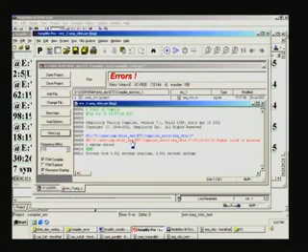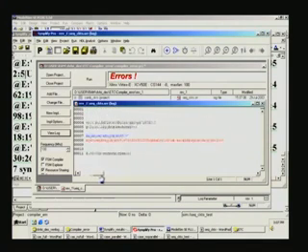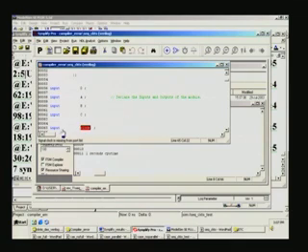It is once again the same, except that this time it is reporting differently. Signal clock is missing from port list, that is what it says here. If I double click, it goes to precisely the same statement, input clock, it is highlighting here. So the simplified tool is marginally better in reporting compiler errors.